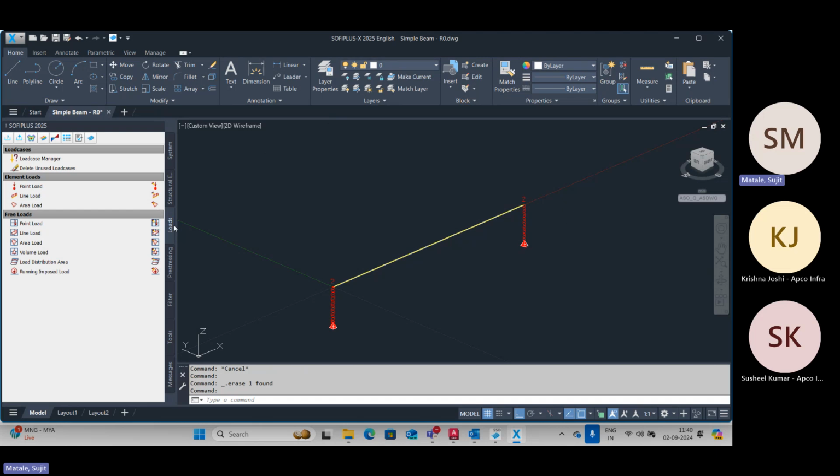So it will speak, based on those actions, okay, types, winds. So your load cases under wind load or seismic load can be in X, Y, and Z direction. But your factors, which are defined in the IRC, that table, are as per your actions. So your actions will be governing your load factors. And there can be multiple load cases in those actions containing the same load factor. That's why there comes a need to define something called actions, or in MIDAS it is called load types.